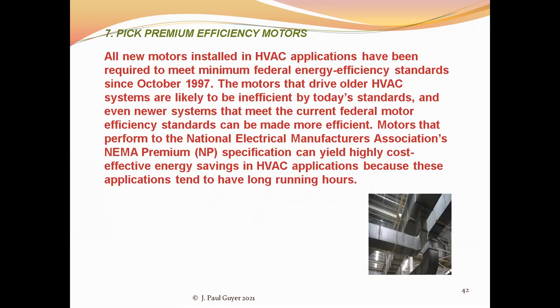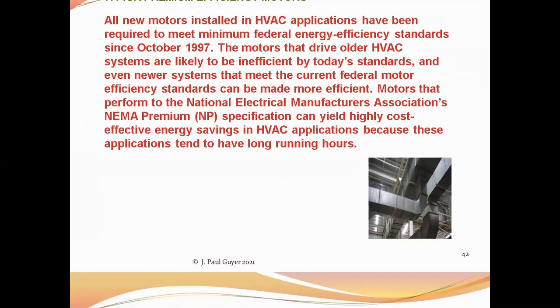And then the premium efficiency motors, this is an industry designation for higher efficiency motors, and you should look at the possibility of exchanging an older non-premium efficiency motor for a newer premium efficiency motor, because you'll achieve some substantive energy improvements there.